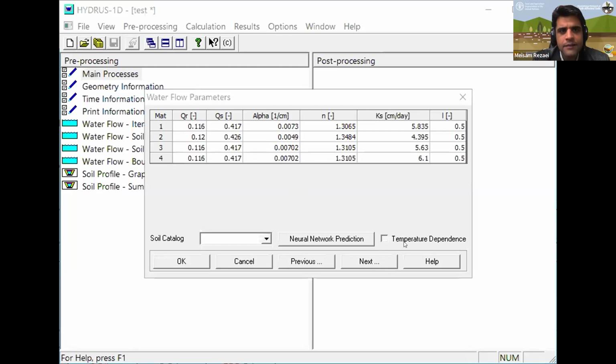For I, normally in dry land, we use 0.05. And sometimes we can change it based on experience, and sometimes we can optimize it based on the water retention data set. In the Excel file, we can optimize it based on the data that we provide. Maybe you can give some reference on how it can be chosen for other regions? As I remember, van Genuchten in 1989 had a publication on that. And maybe later on, because I don't have it now, I will share the document with you and you can send it to the participants. Okay? Yeah, okay. They try to evaluate this parameter.